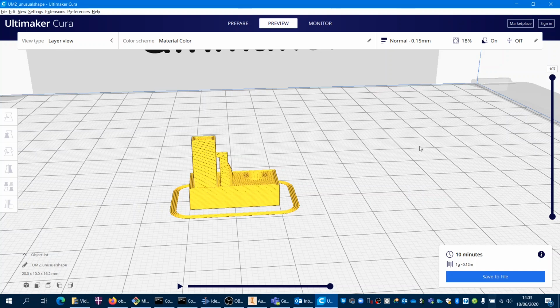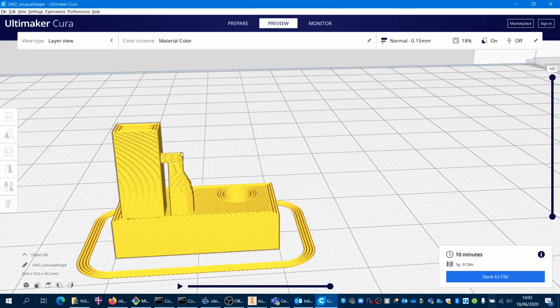The other purpose is to see that the bed is level, because when it prints this, it should come out nice and evenly. If, for instance, it's very thin at one side, it means that the bed needs leveling and it's not going to print the part evenly. So you should stop the print, level the bed, start again. When all is well, it will then continue drawing this central piece. You can see the pin and you can see the scaffolding that it's built underneath. You'll be able to easily break this away when the part is finished printing.